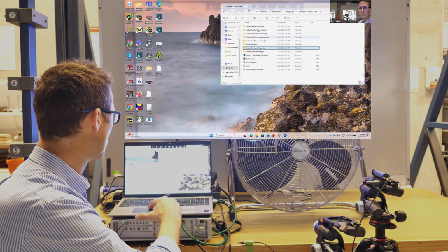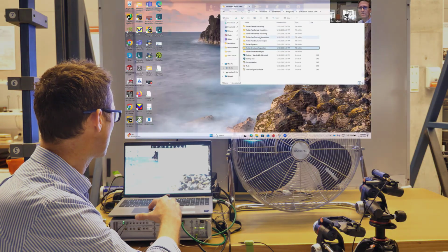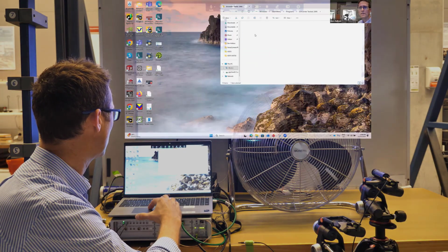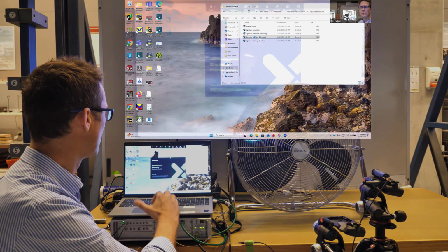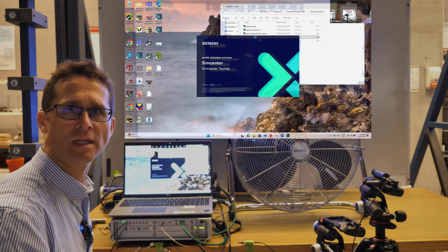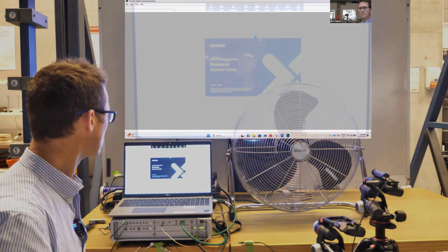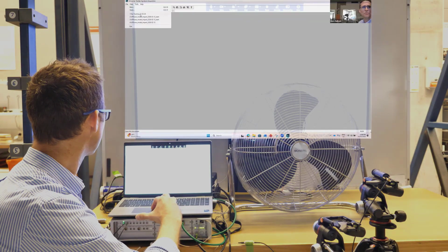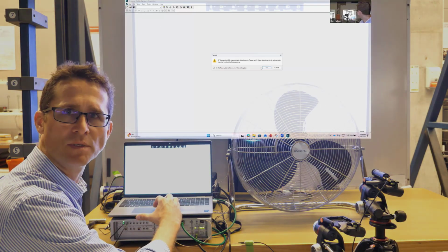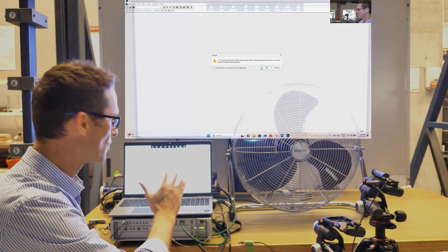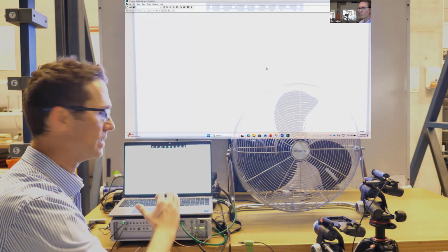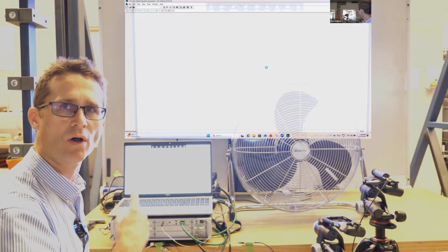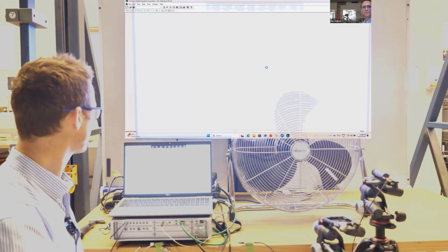I'll also be using signature testing advanced. We'll have a little look initially at signature testing advanced, because this is the work package or the workbook that is used, the solution that is used for making measurements where we're interested in tracking, for example, vibration with respect to a particular order of a rotating machine frequency.